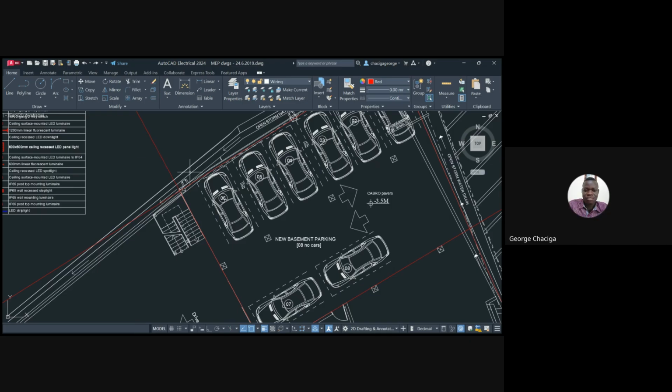Remember this distance we measured from wall to wall, from the extreme end to the extreme end. We want to see where we're offsetting from this point to where our first lighting fixture would be. So you're dividing by 8 because you're going to get half of this distance: we move away from here, and also I'll move away from here. So if I get that, which is 2, you copy that distance.